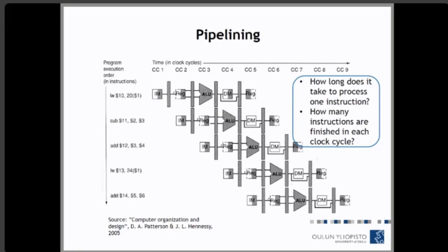But you can change it in a manner that you don't hurt the logic, so you identify the instructions, or instruction segments, that are independent of each other, and then you move them around. And also you can check whether these consecutive instructions will have a hazard or not.